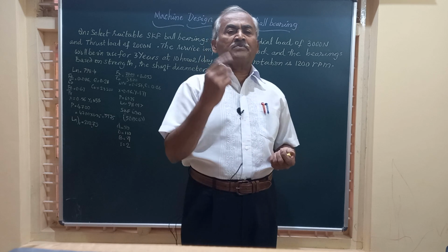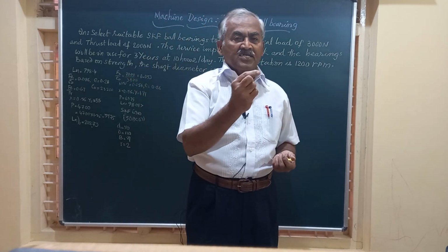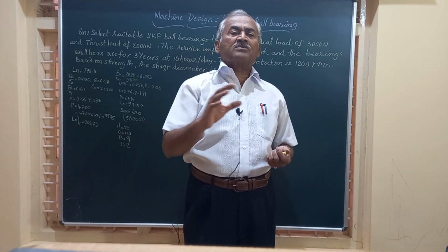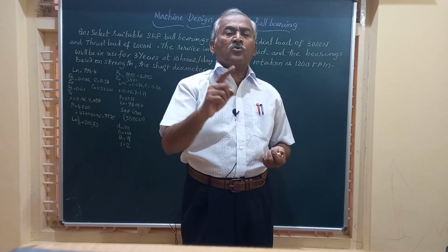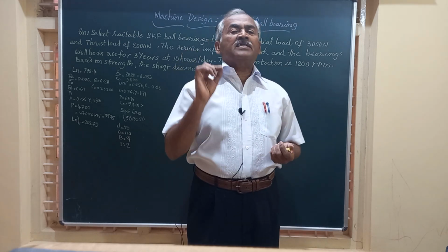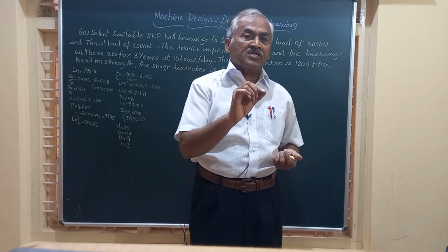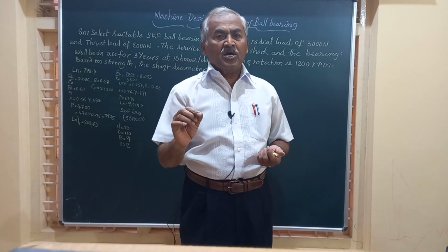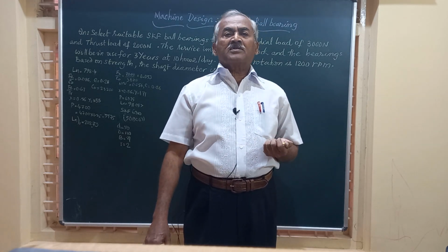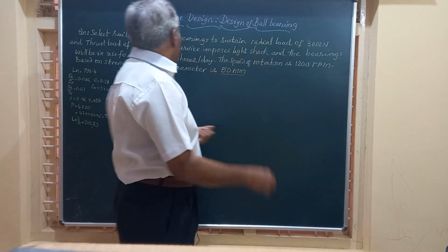Generally there are two types of load. One is the radial load and the other is the axial load or the thrust load. In the design of these ball bearings, the axial load and the radial load will be given, and it will be specified in the problem what service is required, for how many years this bearing will be in use, and at what RPM the shaft is to rotate. So friends, let us see the problem for today's video.